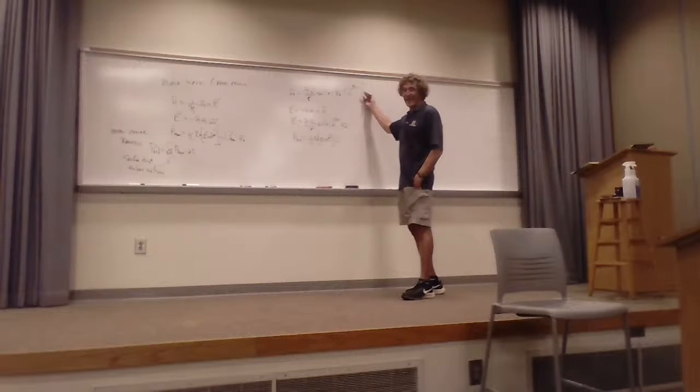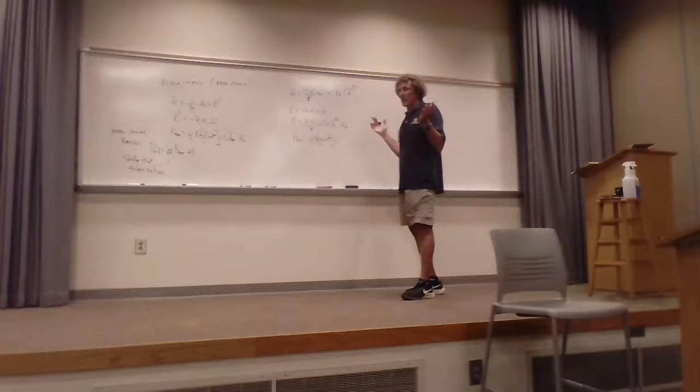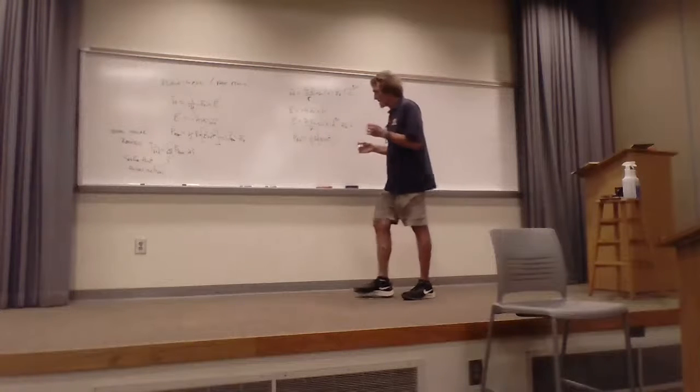There's no e to the minus alpha R. I know it's lossless, so I can do it 2 ways. I can say, well, it's a propagating wave. That's the power density, 1/2 magnitude of the E field squared over eta. Or I can say it's 1/2 times eta times H squared. Either one will do the same thing because E and H are interrelated by that.